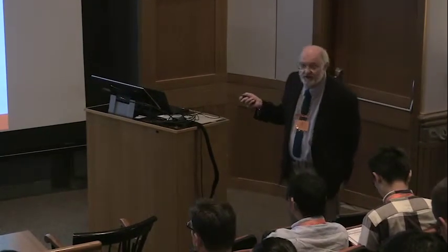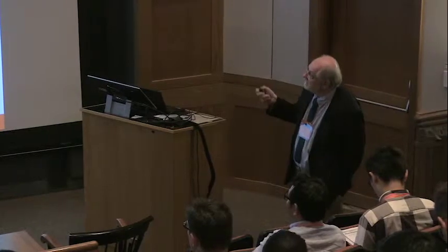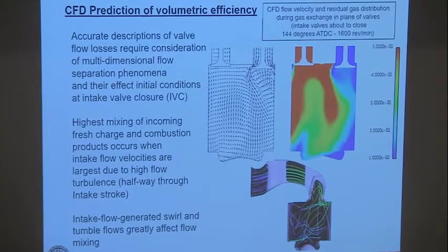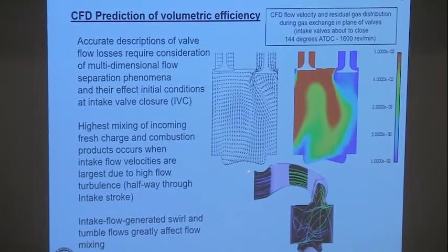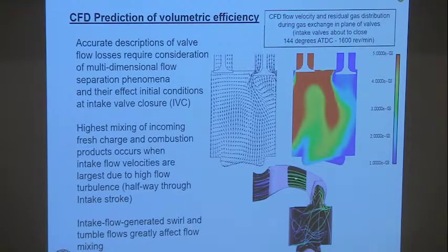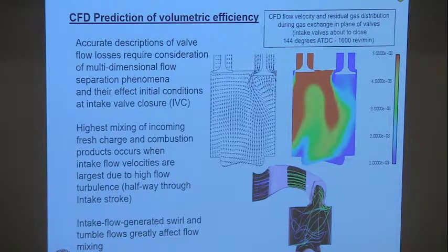So we spoke about volumetric efficiency. Well, you can calculate volumetric efficiency. Of course, there's always the issue of accuracy and so on, but this just gives an example of the kinds of things you can resolve with CFD. Here's that picture that I showed of the intake flow. These are streamlines. You want to make sure that these are nice and smooth and not separating from the flow passages so that you minimize losses in the flow.